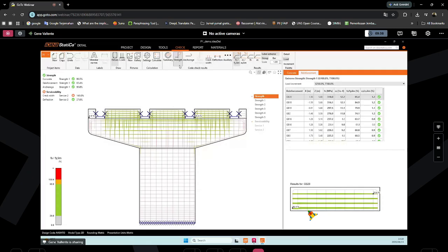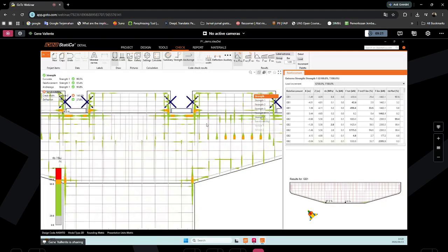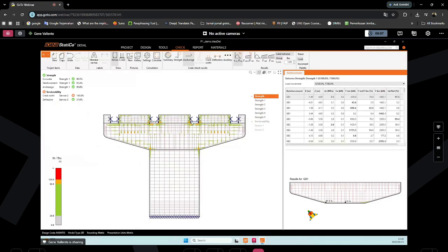And if you go to the anchorage tab, okay, it's a little bit frozen. Just give it a quick second. You can also see what the anchorage stresses are here. Here in every reinforcement, there are values for each reinforcement. You have here the limits and also the bond stress. And if you go to serviceability, you have here the crack width as well.